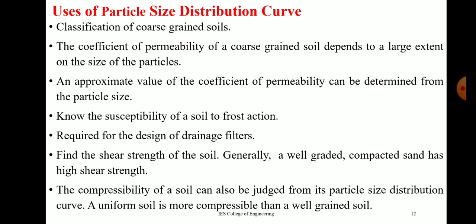We can find the shear strength of the soil, and generally a well-graded compacted sand has high shear strength, and the compressibility of a soil can also be judged from its particle size distribution curve. A uniform soil is more compressible than a well-graded soil.